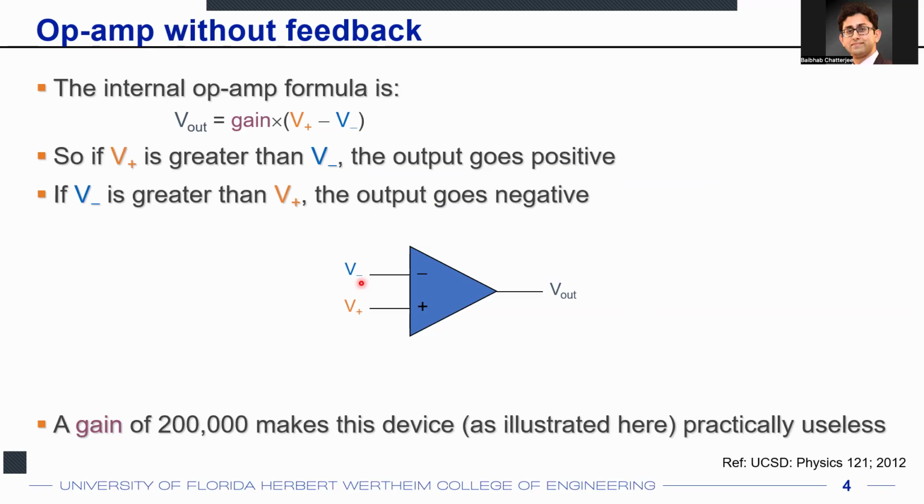The second thing is that, of course, there will be VDD and ground in the system, and your VDD could be 5 volt, your VSS could be minus 5 volt. So your signals will be clipped. Instead of 200 volts, all you'll be seeing is 5 volt clipped signals, square waves.